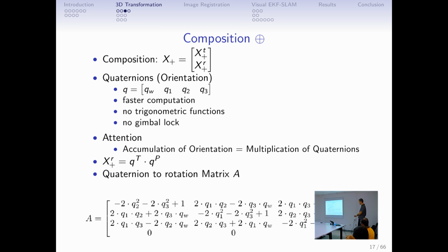And that's already the estimation of the rotation. Because we are taking the quaternion of our transformation, so what's coming from the visual odometry, multiplied by the quaternion of our pose, and this is our estimation of the orientation. And another fact, we can put the quaternion into a rotation matrix as we see here, again without the use of trigonometric functions.